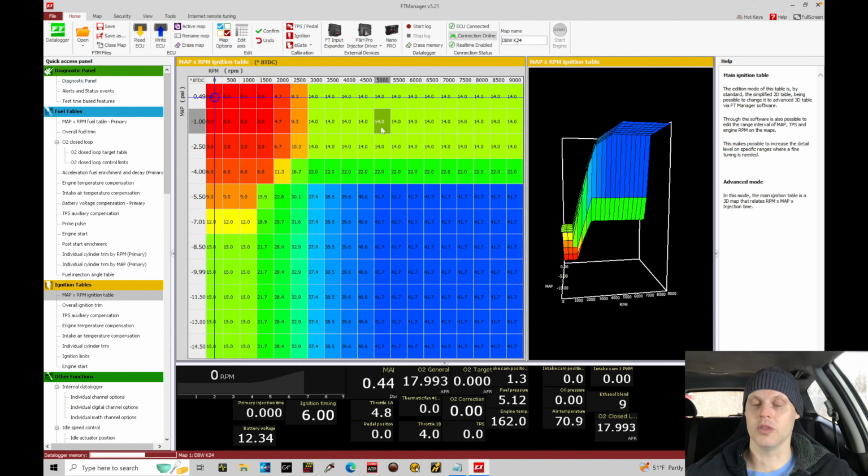Now, starting off with low spark timing like this, we're going to have really low power output of the engine. That's okay, not a big deal. I'd rather be safe and dial in the fuel table than just jumping in here and running high spark timing and doing everything all at one time. It makes things a little bit chaotic and not organized for calibrating and tuning. So we're starting off with a conservative value to keep things safe, keep things in order.